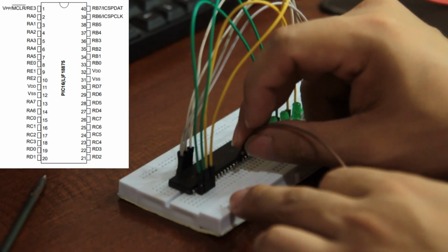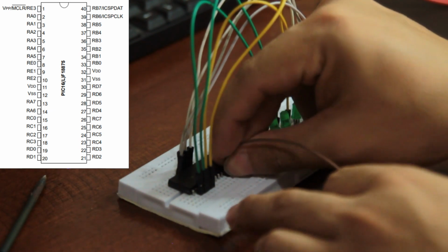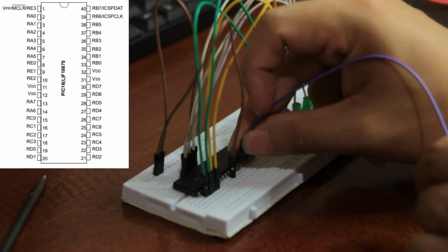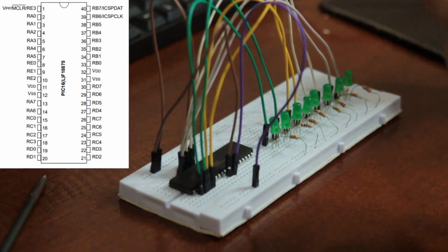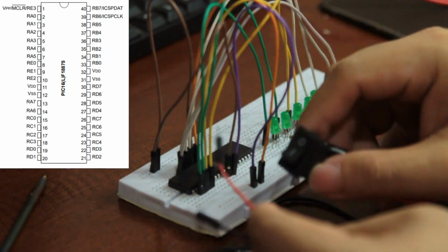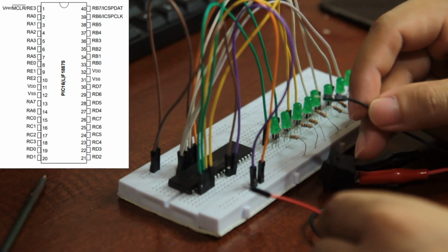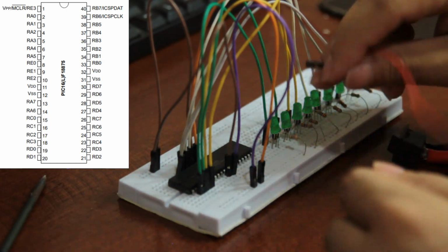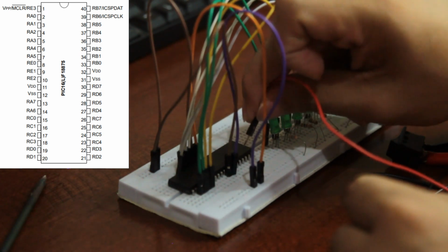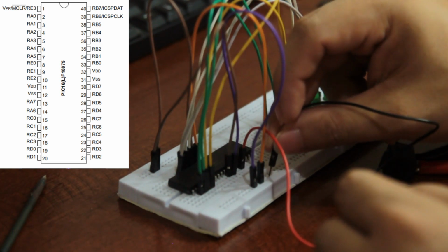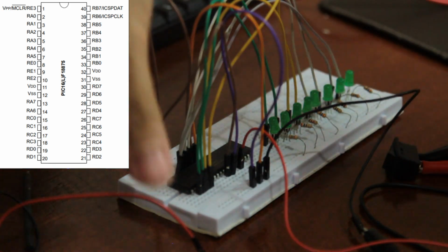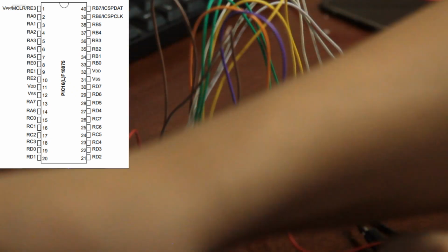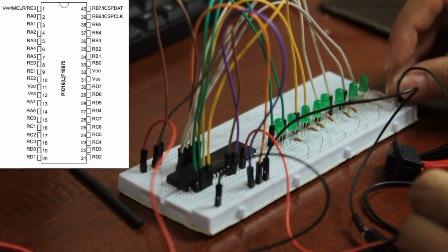Let's connect all VDD to the positive terminal. So 11th slot and 32nd slot will be connected to the positive terminal. Then VSS, 12th slot, here, ground. And the 31st slot, ground. So I have here a switch with 2 pins. The positive pin of the switch will be connected to the assigned pin for the switch in the microchip. So RC0 is connected in the 15th slot here. Then the negative pin of the switch to the ground. Then let's connect the positive terminal and negative terminal. Let's also connect another negative here for the LEDs.